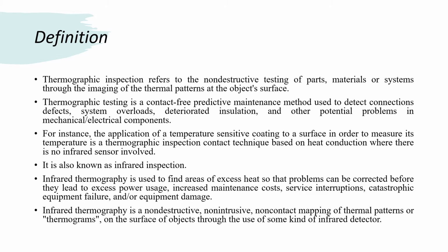Infrared thermography is used to find areas of excess heat so that problems can be corrected before they lead to excess power usage, increased maintenance cost, service interruptions, catastrophic equipment failure, and equipment damage.